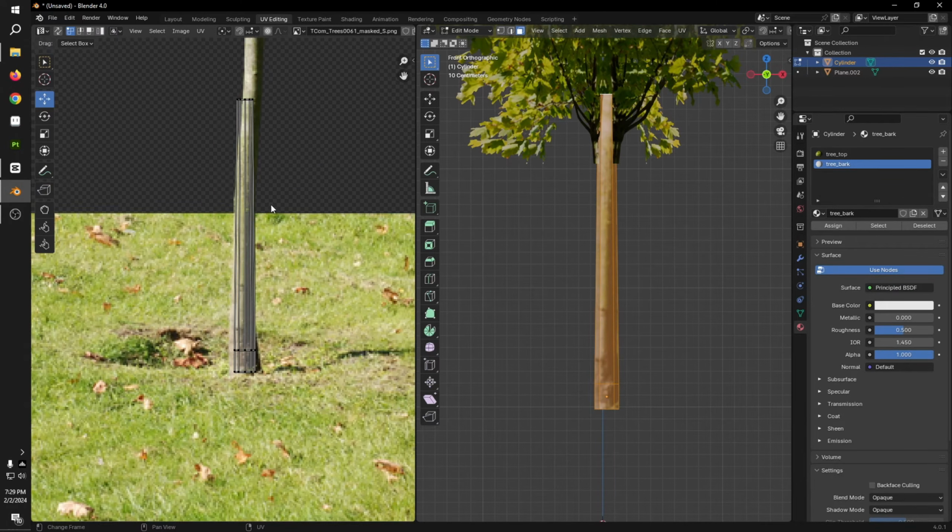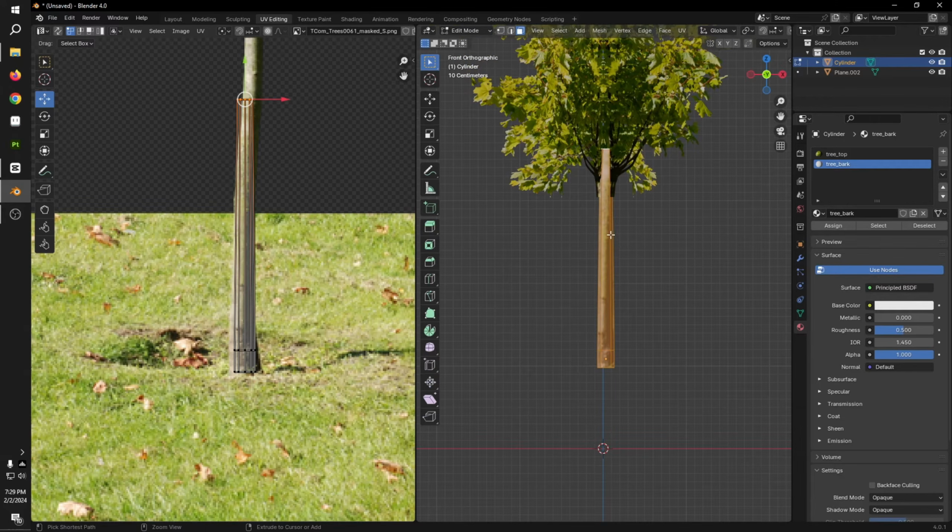There aren't any intersections for this to work with. So for now, what we're going to do is hit A on everything, Control R, take your cursor to the middle of it, Control R, and you should get this. And now what you want to do is increase your cuts by scrolling your mouse wheel. I'm just going to get this much. I think this is about right.